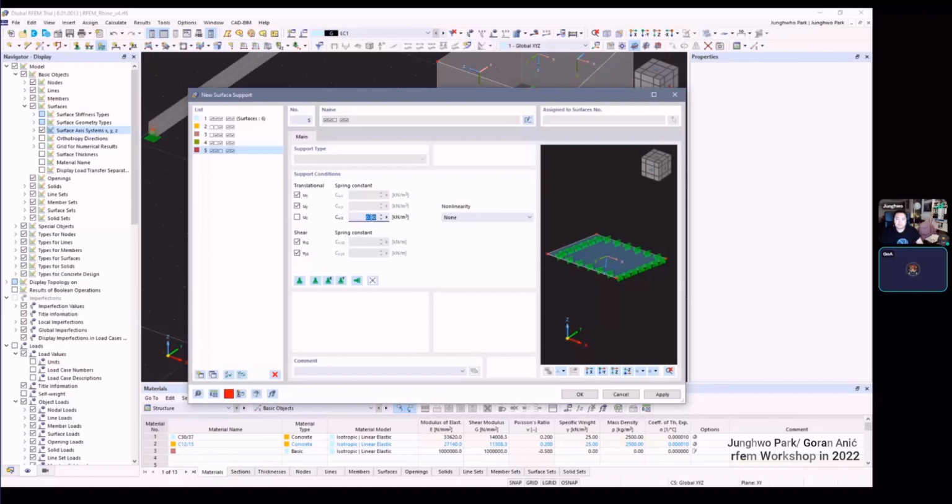For example, this depends on soil condition, you know. If we have really bad soil, this is some part where the geotechnical engineer is in charge. We take this value from their reports, and it's directly connected with the settlement of the foundation.